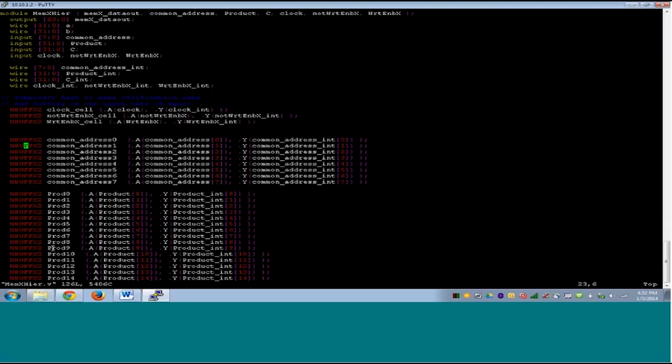So now the RTL designer, for some reason, chose to instantiate some buffers in this RTL. Now, in this case, this RTL is not technology independent. Why? Because this is using some buffers from a particular standard cell library. If I want to use this RTL with some other standard cell library from some other provider, I'll have to make sure that these buffers get replaced.